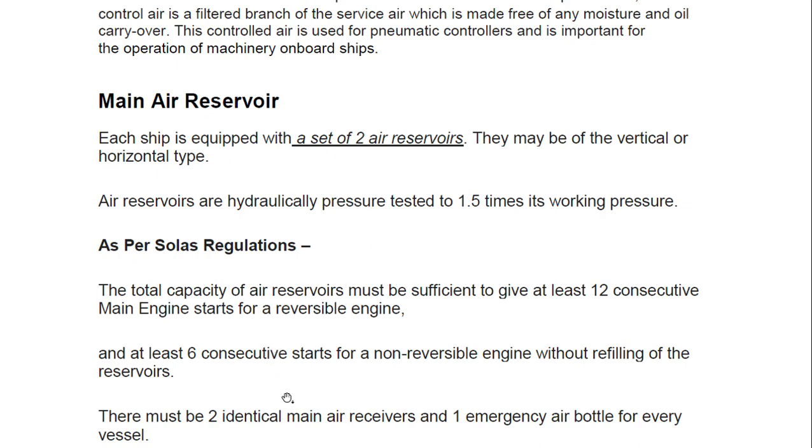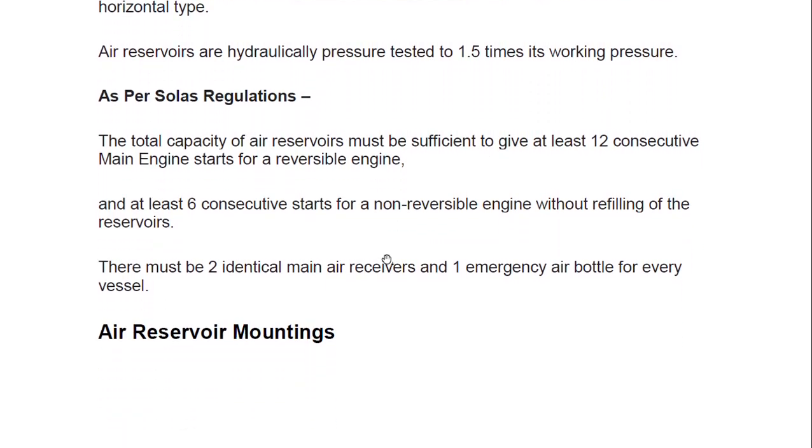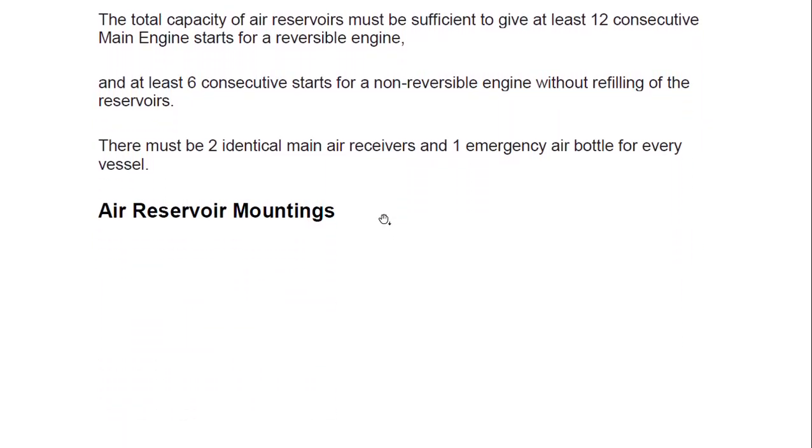There must be 2 identical main air receivers and 1 emergency air bottle for every vessel. So that must be 2 in number. 6 consecutive starts for non-reversible, 12 consecutive starts for reversible. And for the air compressor, in 1 hour it must be able to fill the complete bottle from 0 bar to 30 bar. Okay, so these are required. This is what the SOLAS has to say.